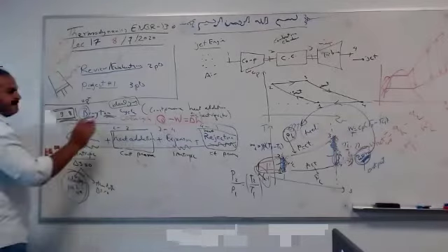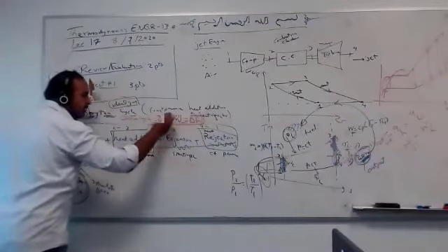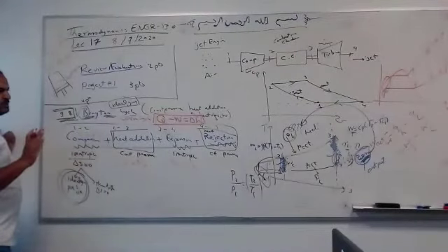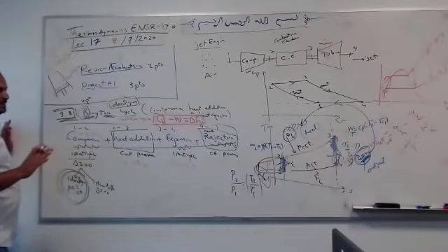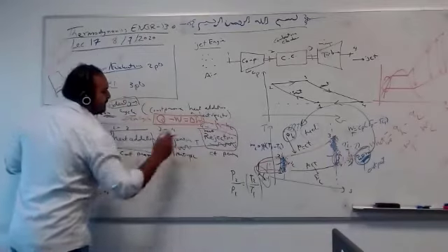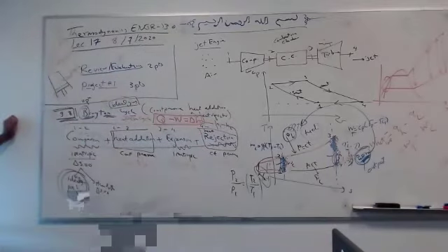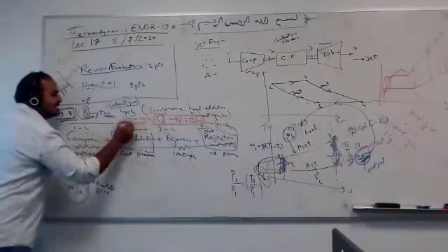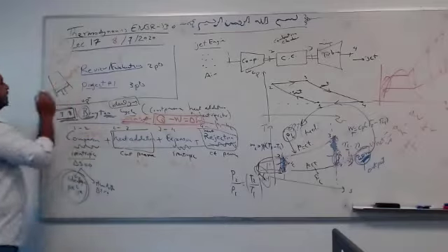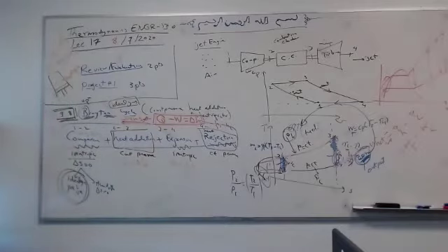So this is the first law of thermodynamics for an open system, assuming steady state, and we neglect all the kinetic and potential energies. So this is input and output: H1 minus H2, H3 minus H1, and so on. This is input minus output, because it's an open system, open cycle, unlike closed systems in Otto, diesel, dual, Carnot.